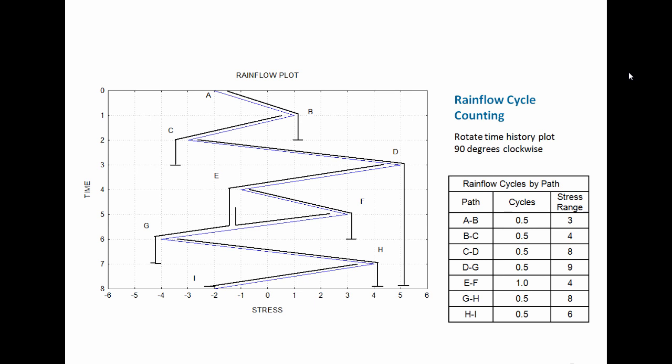But why even bother to bin our data? Right here we have the cycles and stress ranges, and we can convert stress range to amplitude just by dividing by 2. We could just feed this data directly into our Miner's rule summation. Why even bother with binning?